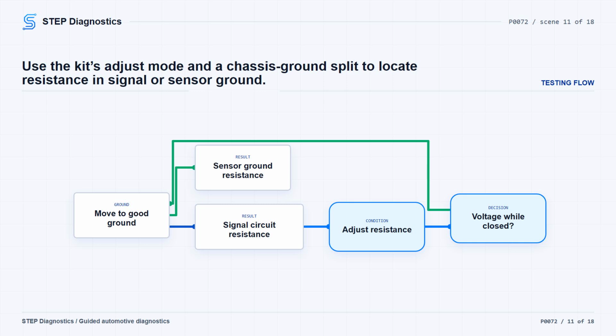Isolate the suspect circuit and measure resistance between the sensor and controller connectors. Typically, it should be less than 3.0 ohms. If the circuit itself checks clean, go back through the connector path carefully before blaming the controller. If your test path reaches an unclear branch, pause, recheck the earlier diagnostic path and avoid guessing.